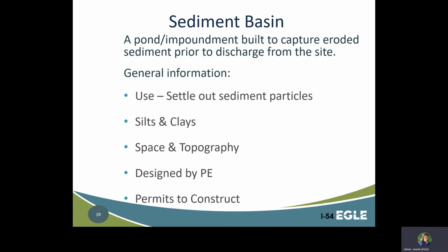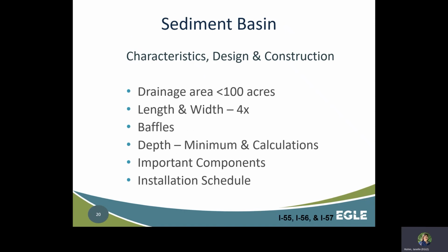Sediment basins need to be designed by a professional engineer to ensure the basin will adequately contain sediment-laden runoff from the entire drainage area. In-stream sediment basins, also known as sediment traps, are typically not recommended and may not be constructed without a permit. Here is some basic information about design of sediment basins.